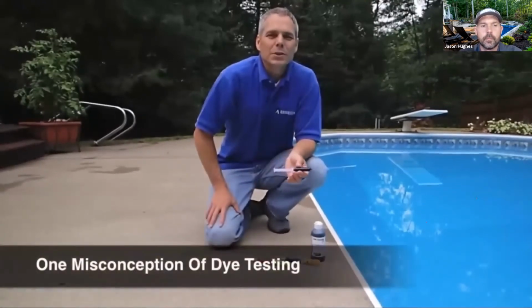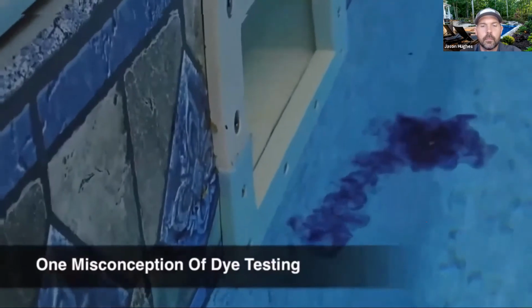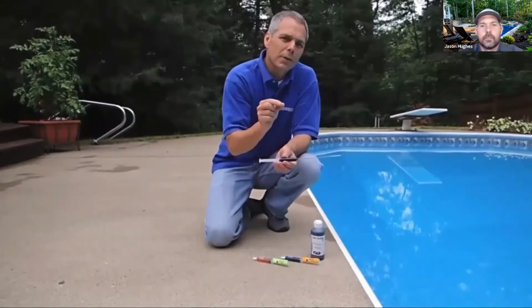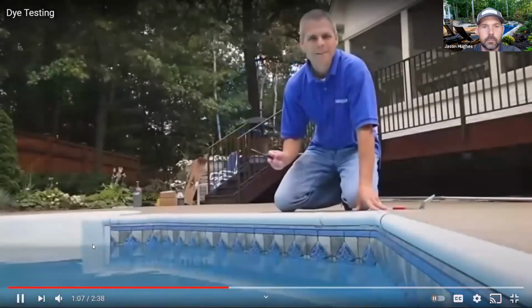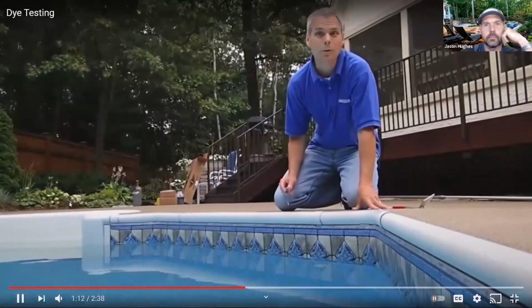Common misconception is that one would be able to just put a big cloud of dye into the pool and watch where that dye moves to identify where the leaks are. That's not possible. With dye testing, we're putting a very small amount of dye very close to someplace we already suspect is leaking. The first step is to assure that the water is calm and we don't have any currents. So I've turned off the pool equipment.